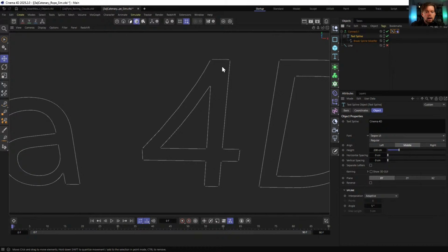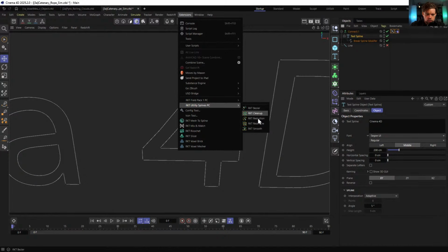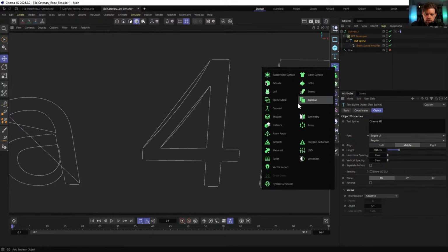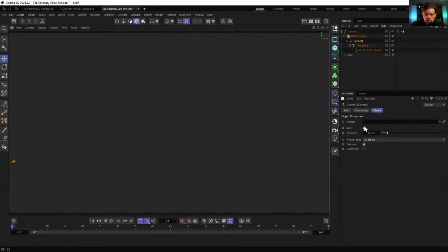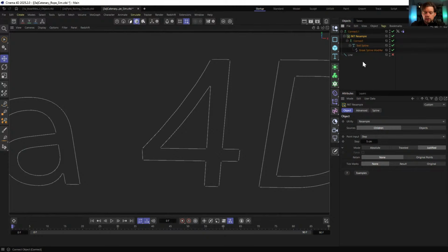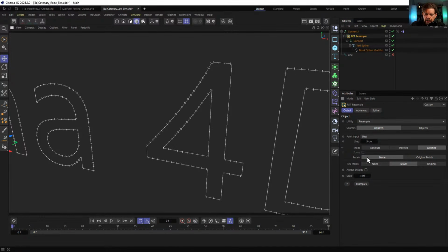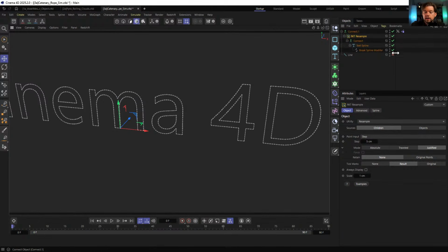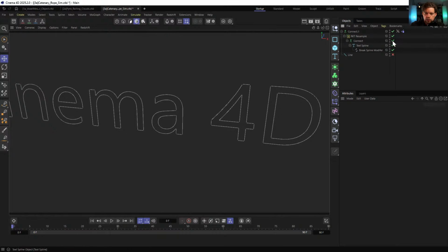So the easiest thing would be for me to throw this into the Rocket Lasso utility splines. So I could put this into the Rocket resample. And oh, is it not going to consume it unless that's in a connect? Yeah, this also wants it to be in a connect, but I could say resample it, and here's what's cool. I can double click here, and now we can see how it's resampling. And right now it's a step of 5, and all of those are getting subdivided. So there's some points for it to work from in theory. Still parametric. I got all those subdivisions in there.